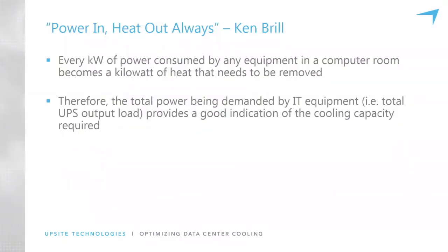I began my career working with Ken Brill. He founded the Uptime Institute and Upsite Technologies, and Ken often reminded people that it was always power in, heat out, always. He used this phrase to bring awareness to the relationship between the IT load and the required cooling. If you know the IT load, basically the UPS output load, then you have a good indication of what the cooling capacity is.